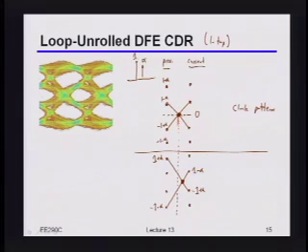Yeah, exactly. So when the transition crosses the dotted line, that's really the right time for you to say, is the thing early or is the thing late, right? Okay, so what that basically says is that now, if I want to make this thing work, what I should basically do is, on this arc, meaning on the arc that goes from 1 plus alpha to -1 plus alpha, instead of deciding whether it's early or late based on slicing at 0, instead what I should actually do is slice at wherever that voltage is that crosses that dotted line. Okay, so I'm just going to draw a dotted red line there, and another dotted red line here.